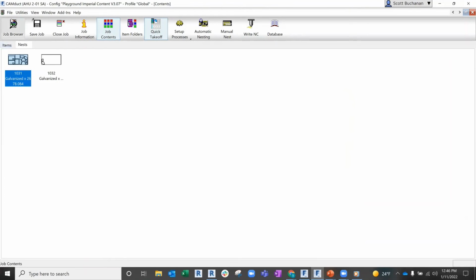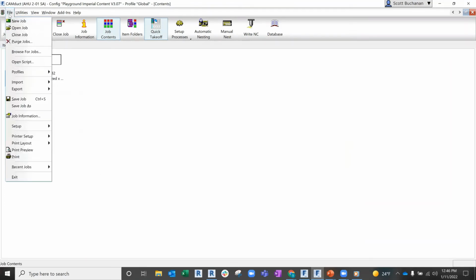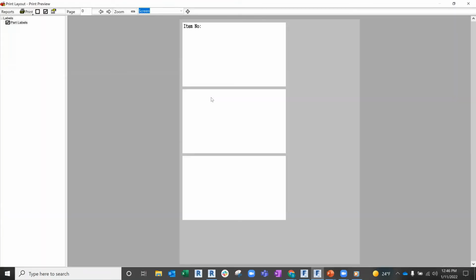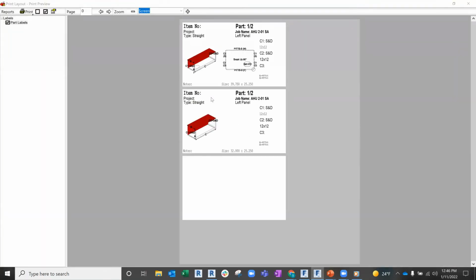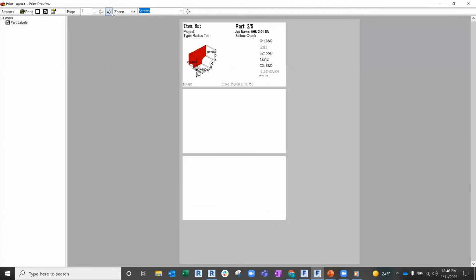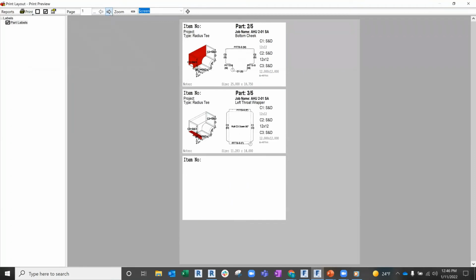We can print out labels for each of these now that we've got, that's been pushed out. So think about, we've got a part label. I'll just do a preview here. So as that thing's getting burnt, right? I've got my label printer that's going. That stuff's getting printed out. I'm going to pull off the stickies and stick it on the side of each of those, inside of there, right? So we can see there's those particular parts. And these are all customizable too to match certain shop standards.